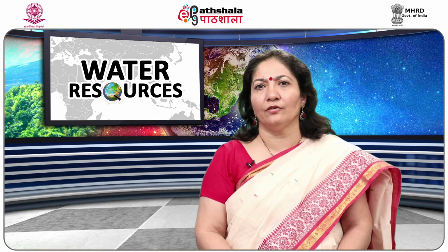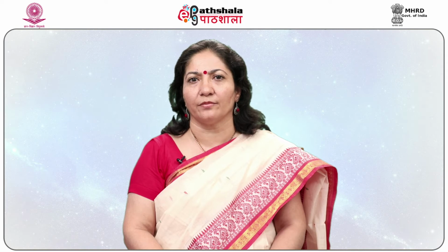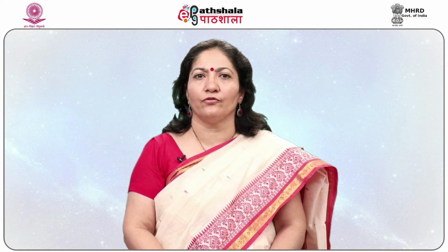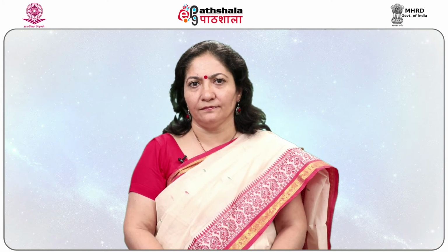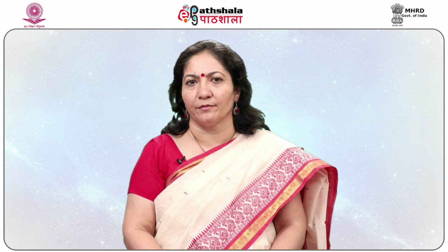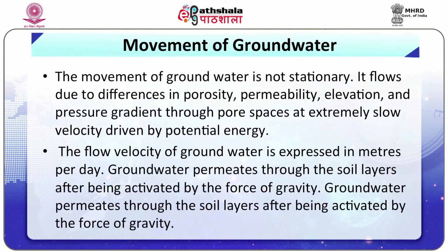If the permeability of the ground is uniform and there is an increasing gradient of slope of the water table, then the velocity of groundwater flow increases. This is called hydraulic gradient. Table 1.3 shows the permeability for sediments. In rocks with fractures, permeability is determined by the size of the openings, the degree of interconnectedness and the amount of open space.